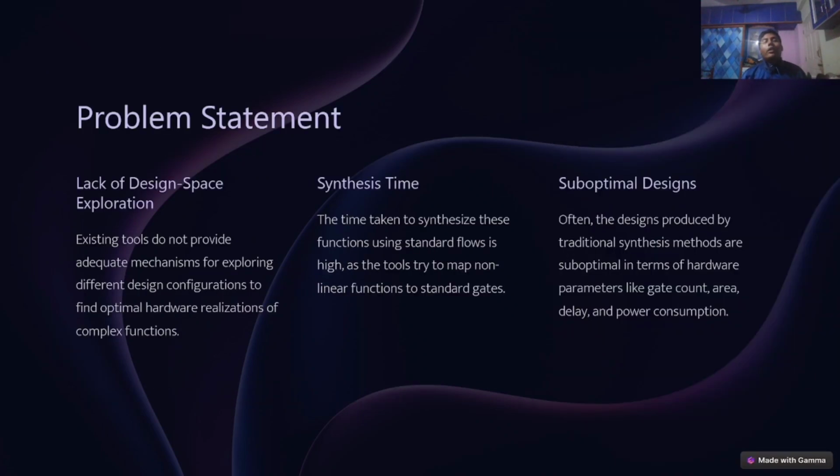The problem statement was lack of design space, synthesis time, and suboptimal design. Existing tools do not provide an adaptive mechanism for exploring different design configurations to find the optimal hardware realization of complex functions. That was the lack of design space. Synthesis time means the time taken to synthesize this function using the standard flow is high, as the tool tries to map nonlinear functions to standard gates, so it takes time. And suboptimal design: often the designs produced by traditional synthesis methods are suboptimal in terms of hardware parameters like gate count, area, delay, and power consumption.